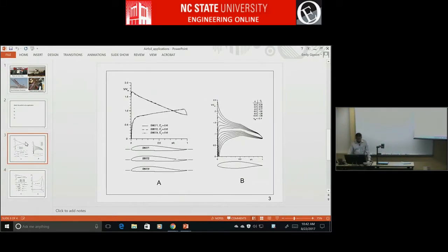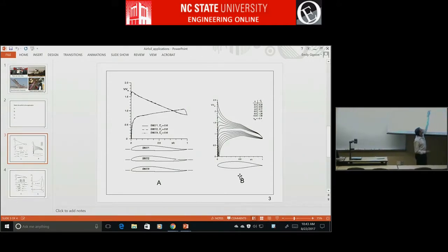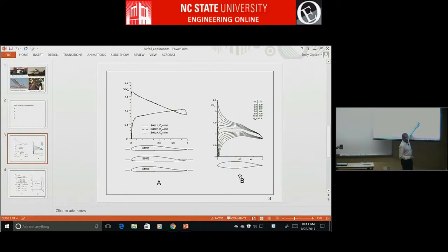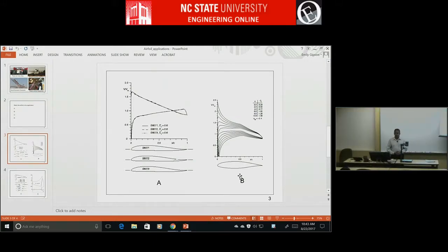And the last one is this. This is the airfoil for the NLF airfoil, natural laminar flow airfoil, for the general aviation airplane or the home built airplane. And here the pressure distribution is tailored so that in the cruise condition, so these two are the cruise condition, you always have increasing velocity up to something like 50% or 70% depending on the application. That supports a lot of laminar flow, and then you make it turbulent flow here. Laminar flow is less skin friction drag, which is really what you want for cruise.